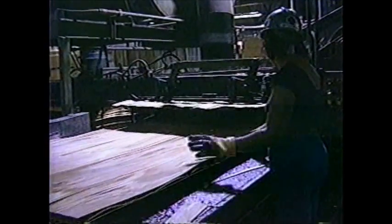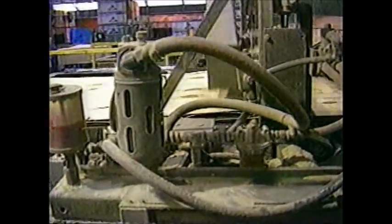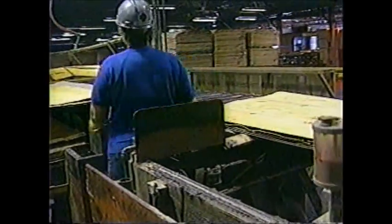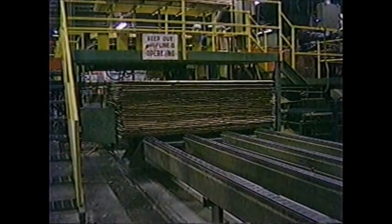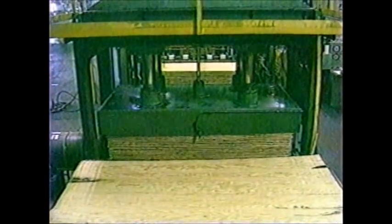Glue is again applied, a crossband layer is laid down, adhesive applied, and the outer ply is laid down, completing a rough 5-ply, 5-layer panel. A saw clamps the panel and cuts between face and back sheets to separate any crossband pieces which are shared between adjacent panels. The rough, oversized panel is then conveyed to a pre-press, which employs pressure but no heat, to form an initial panel bond. This minimizes shifting of panel plies in the loading of the plywood hot press.